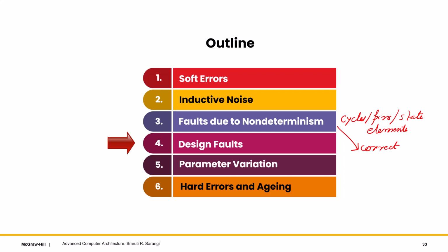It is just that the state of the cache will vary from run to run, and thus debugging will be hard in case some problem is found in the CPU. So that is why, the external output being correct, we would also like some degree of internal determinism to ensure that bugs can be reproduced in the lab, and a higher level of correctness guarantee can be provided.